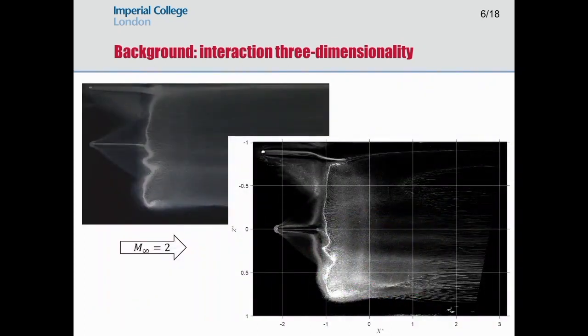We characterized the three-dimensionality of our wind tunnel. So this is oil flow visualization. So we're basically injecting paint into the floor of the wind tunnel, and it settles in regions of low skin friction, so separation and reattachment points. So from this, we can pick out our separation region. Two things to notice. We have a large corner separation, which you can see here. And also, even in the experimental environment, the separation is highly three-dimensional, particularly on this near-side plane.